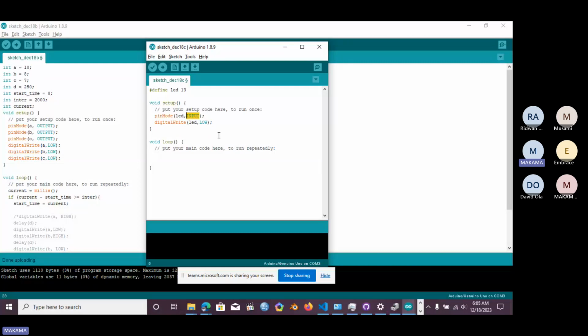There is an inbuilt resistor for each digital input output pin, so once you call that input, the Arduino, with the help of this input function, will automatically enable that input resistor to protect your pin. So please, no need to use external resistors to slow down your work. You will see so many references from so many people, so just be sure which one to choose.